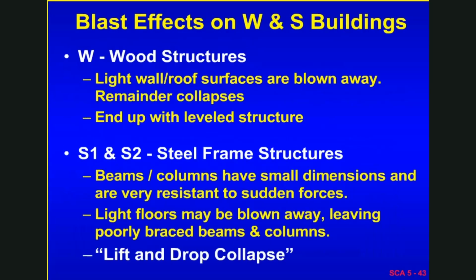So in wood structures, pretty much everything is blown away, and if you happen to be within the structure and within the blast zone, it is very difficult to survive, and what one ends up with is pretty much a pile of sticks. It looks very similar to what a tornado does to a building. In the case of steel frames, what has happened in the past is that the blast pretty much goes past the large steel beams and columns, but it will lift the floors up into the air, and then it'll pretty much drop them down to the lowest level of the building along with all the victims. So I'm calling that a lift and drop collapse, and you'll see that in the next picture.